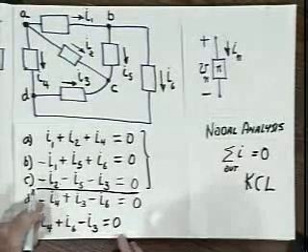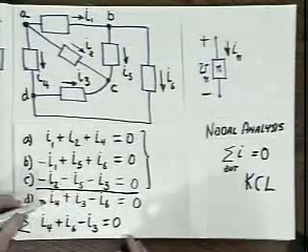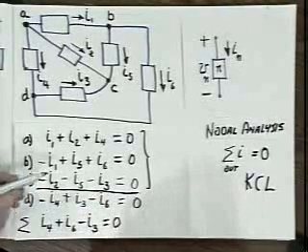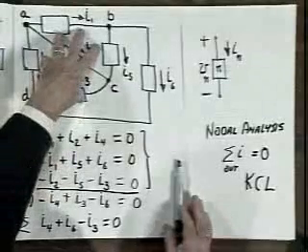And that, as you see, is the same as the equation on D if I multiply by minus 1. If I multiply D by minus 1, I get I4 minus I3 plus I6 equals 0, and that's the equation we got by summing the first three. That applies in general to any network of any number of nodes with two terminal elements. You simply add up the node currents at all the nodes but one, set some of those currents equal to 0, and that set of Kirchhoff's current law equations suffices to describe entirely the behavior of this network under the nodal analysis technique.